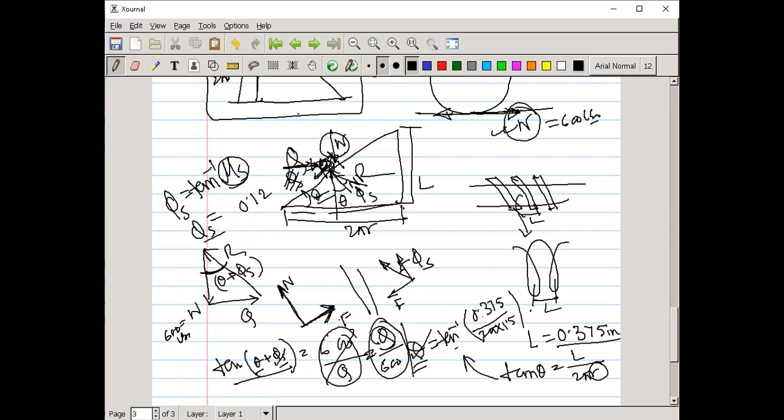Now in the question they ask how much torque is required. So torque is nothing but the Q into the radius of the worm gear. So the worm gear radius is how much? Worm gear radius is 1.5 inch as per the question. So that Q multiplied with 1.5 is the torque.